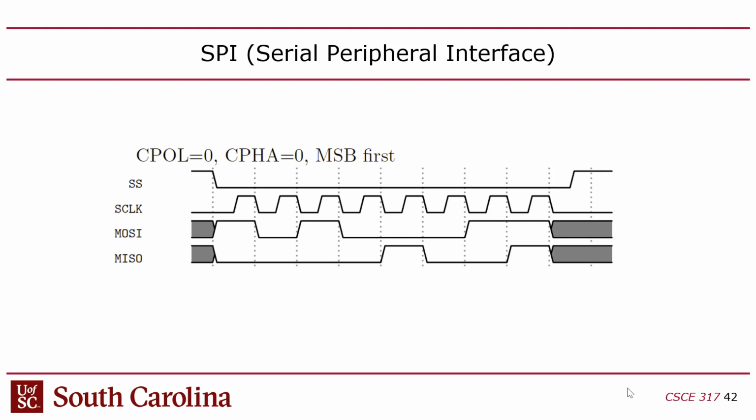So being that it's 0, actually, wait a second, is that labeled wrong? The clock is going to indicate to the other side of the channel when it should be reading. So in this case, we use the first edge. That's right, sorry, I got confused there. This is always the part that's a little hard to get your head around. The first edge of the clock is when you're going to read the first bit.